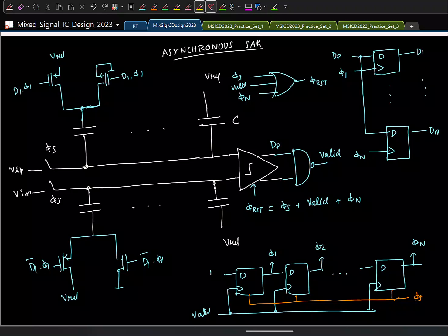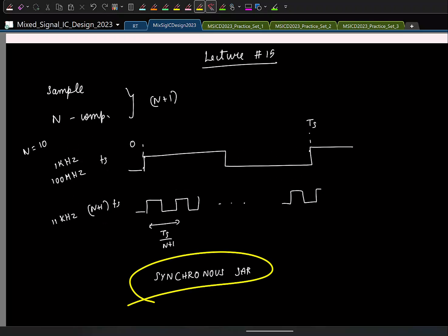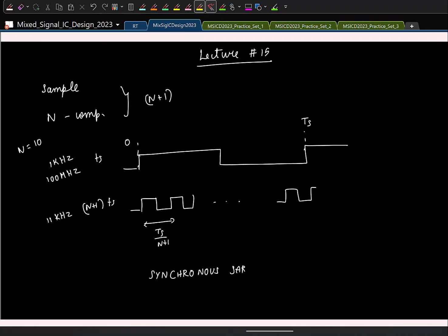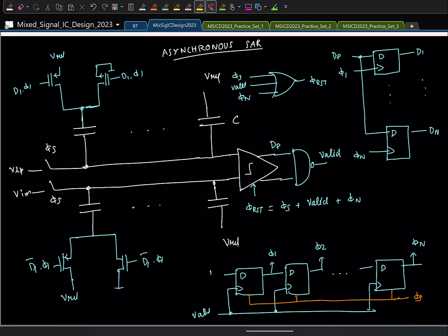Having a fluency in digital circuits is important here, especially because the idea of SAR ADC was known for a very, very long time. But for a long time, we were doing this SAR ADC in a synchronous fashion like this. So you always had to feed a high frequency clock. So it was always built as a low speed ADC. But it was only later people figured out you can do an asynchronous SAR like this, and this is actually not very old. This was done in the late 2000s, I think 2005 or 6, by Mike Chen, who's now a professor at USC.